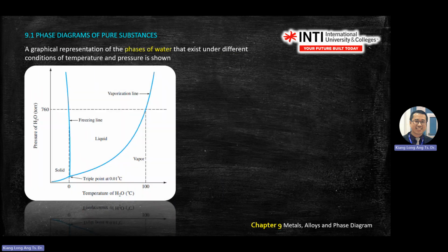So this is another phase diagram. We are now in the phase diagram, this word, phase diagram. This is water. For water, with pressure and temperature, water can behave in three forms: gas, liquid, and solid. So on these blue lines, they are the solubility limit or equilibrium lines. On the left, as long as the point of interest falls in the solid area, then you will see solid. If it falls in liquid, then liquid, vapor, then vapor.